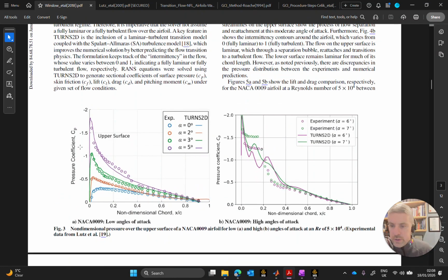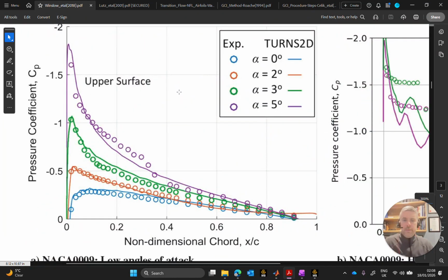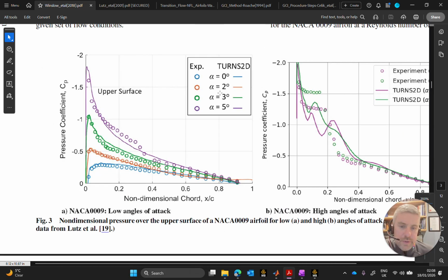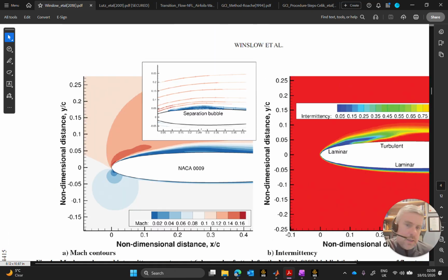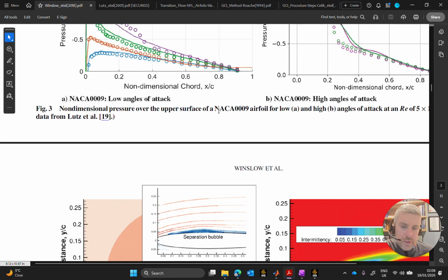But in the first part here, our pressure coefficient table, there's a pressure coefficient measured here for angle of attack 0, 2 degrees, 3 degrees, and 5 degrees. So I would propose there that I put in angle of attack of 2 degrees, 3 degrees, and 5 degrees, run the calculations, see what my minimum pressure coefficient is going to be. So I might just have to change that. Make sure it is reading minimum pressure coefficient, and compare to this data and see does it work. Hopefully it does. So that is, apologies, 0, 2, 3, and 5.